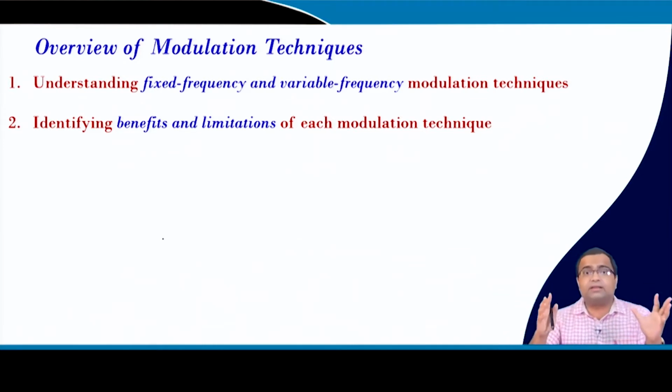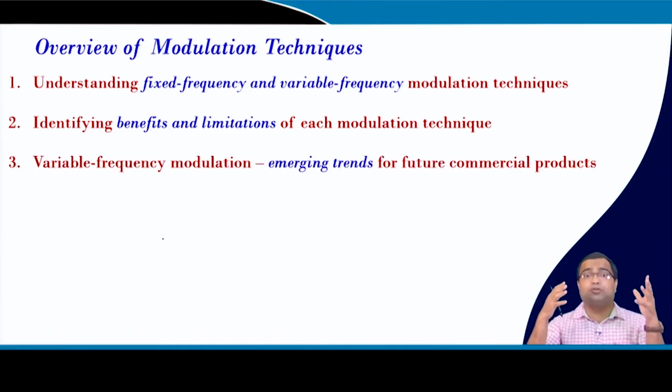So, they are very emerging modulation techniques for wide duty ratio operation, and those variable frequency control methods are the emerging trend in power management products. I mean, power management products will probably see more use of ripple based control, like constant on time, constant off time, and hysteresis control in future. It is already there, but the majority of commercial products are still dominated by fixed frequency current mode and voltage mode control, but in future the ripple based control will be dominant.